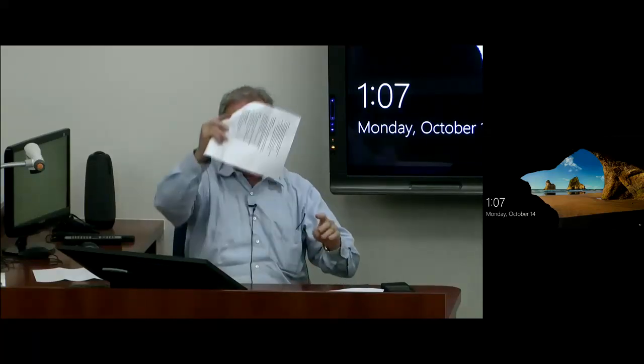The other way is physical vapor deposition. So in physical vapor deposition, let's say I want to coat this sheet of paper. This is my cutting tool. This is going to be my lathe tool. In physical vapor deposition, all this is in vacuum, even the chemical vapor deposition in vacuum. I'll have something here I want to coat, and I'll shoot ions up at it. Bam, bam, bam, bam. And particles will float off and coat the surface. Okay, that's called physical vapor deposition.